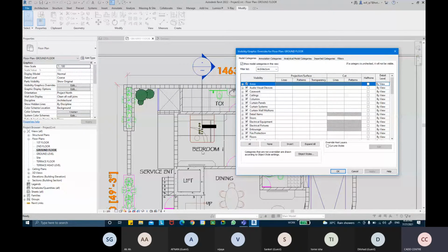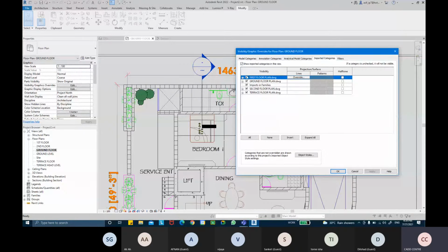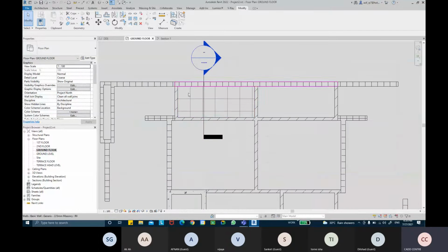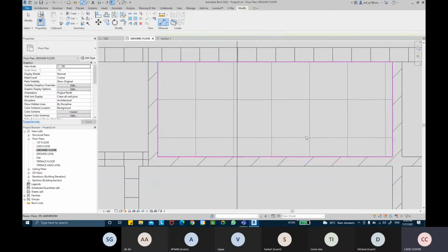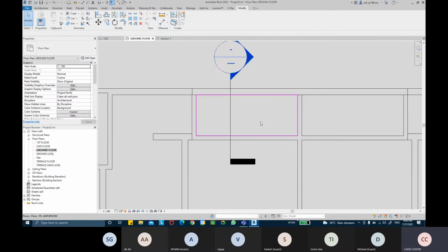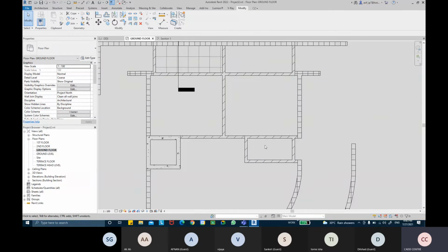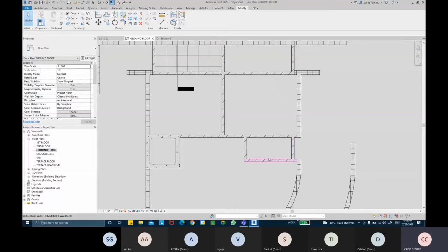This base plan, if it's disturbing a lot, you can turn off those DWG files so that you can clearly understand whether your first tile placement has been done or not. So this is my first tile placement. This should be 600 from there. Correct. So that's 1, 2, 3, like that it goes in order. That's one work done. Similar work you just have to do over here as well, the Kota filling and the floor finishing.